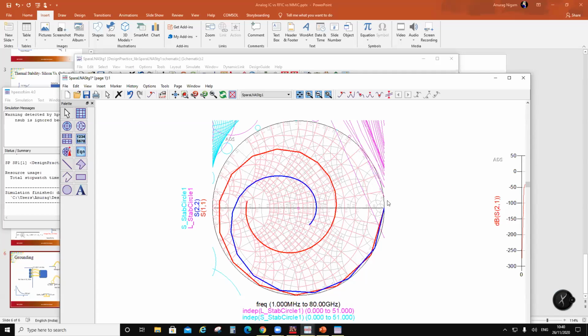And under compression, usually the FETs are going to start oscillating. So you have to do this under power. The K should be written with equations where you're putting a large signal on the input and a small signal on the output. So this is like your X-parameter stuff.